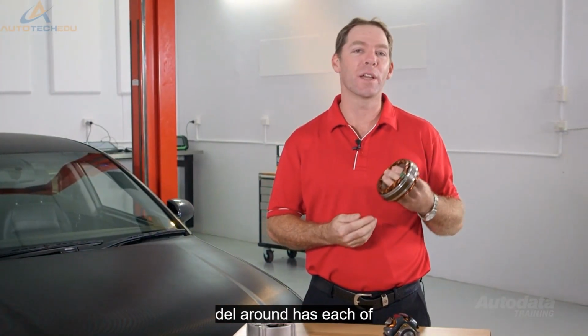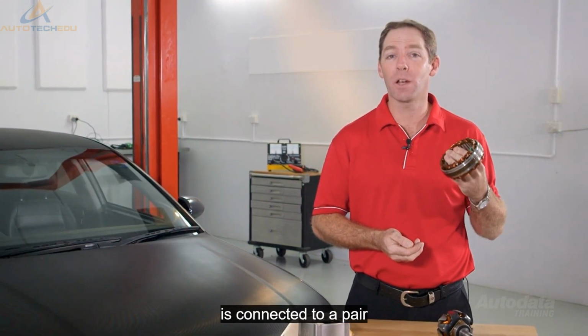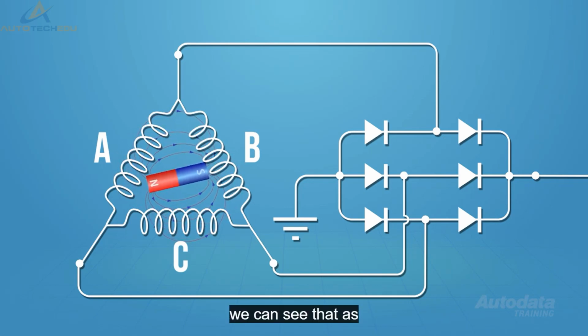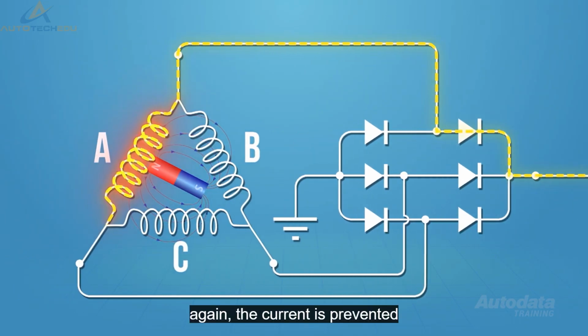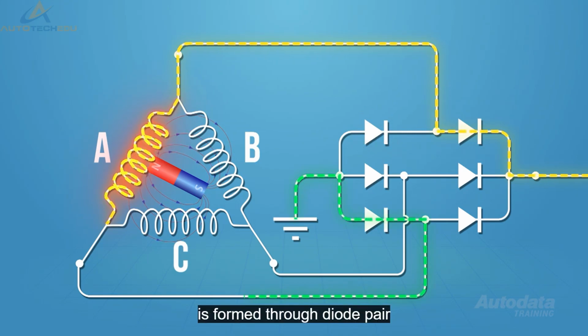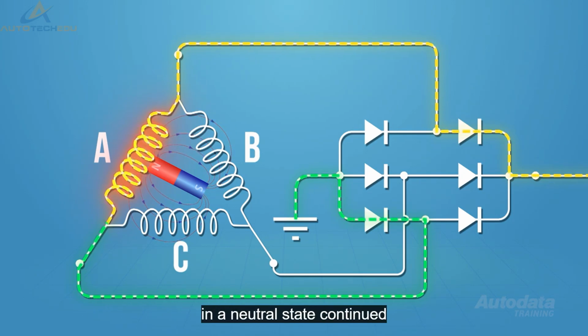A stator that is delta wound has each of its legs connected in parallel. The junction of each is connected to a pair of diodes mounted in the rectifier bridge. In this design, we can see that as the rotor's north pole passes coil A, current flows from the AB junction to the diode pair, where it continues on to battery positive. Again, the current is prevented from travelling to ground due to the negative bias diode. The ground circuit is formed through diode pair 3, then to the coil AC junction. We can see coil B and C are inactive or in a neutral state.